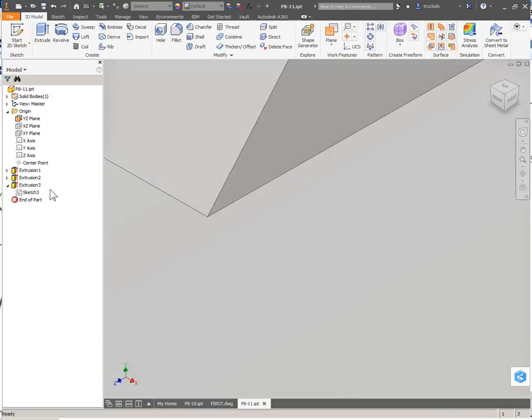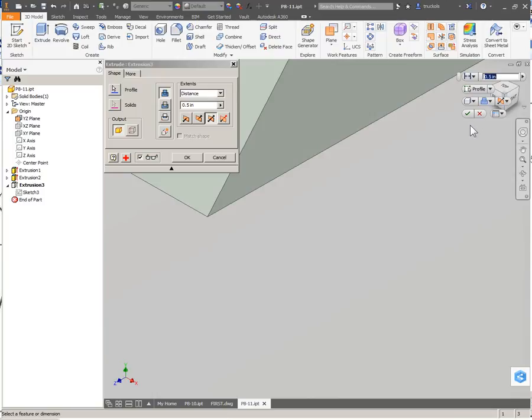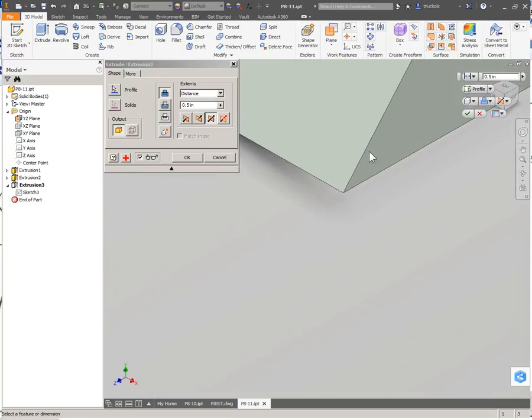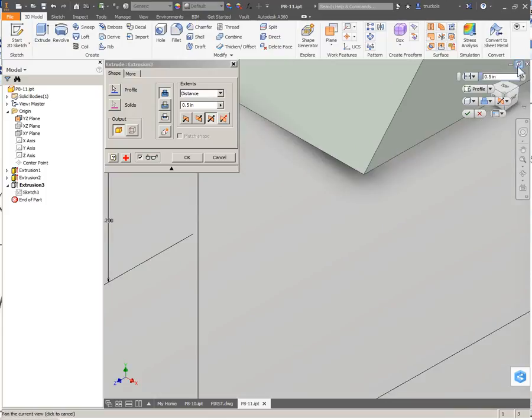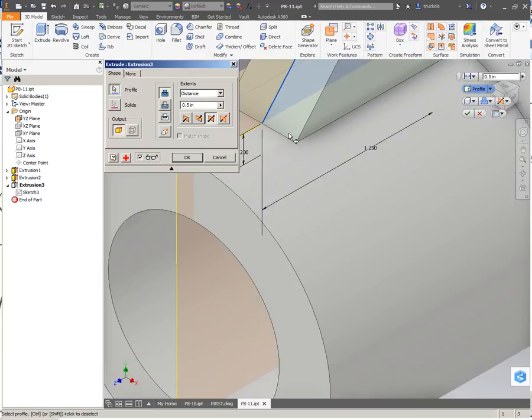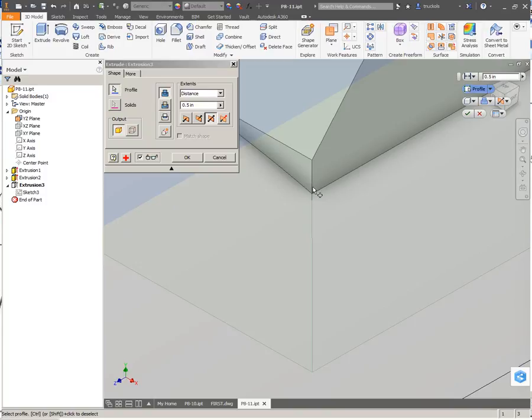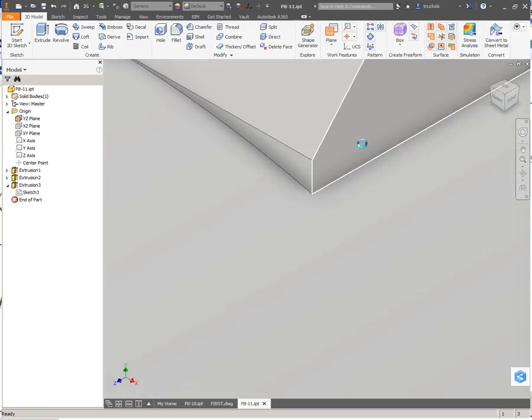I'm going to double click on Extrusion 3 here, which allows me to edit the extrusion. I need to pick that rectangle as part of the profile. It's a little hard to see, but the gap is still there. You can see that shadow over the cylinder. I'm going to click on Profile on this arrow here and then hover until I see that rectangle underneath it light up. You can kind of see it lighting up inside the shape there. I'm going to click on that, and now you notice it created a solid where that was empty. I'm going to click on Check to keep that extrusion.